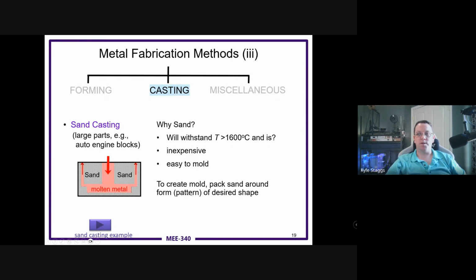A lot of large parts and blocks, engine blocks, heads, large parts, start out in this variety, because they can be made cheaply for large materials while minimizing the machining time, because that's very, very expensive. Those can be pretty gnarly in terms of machining cost from scratch. That's why those parts are typically cast.